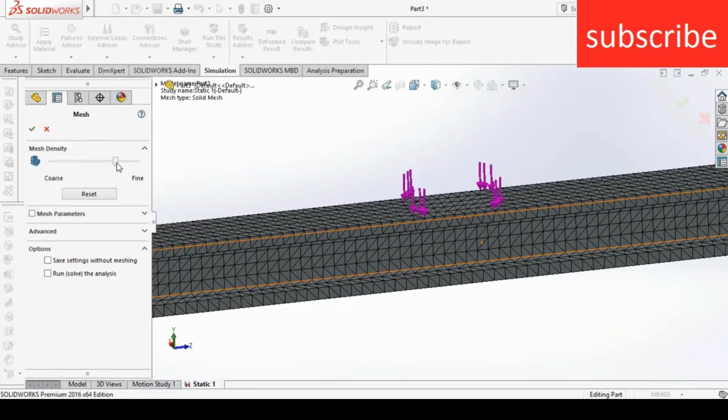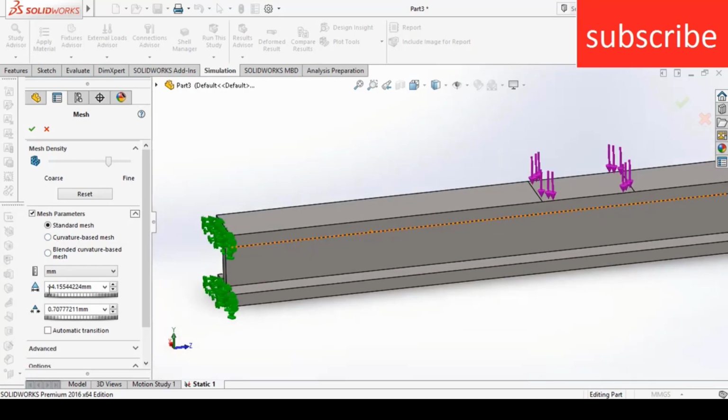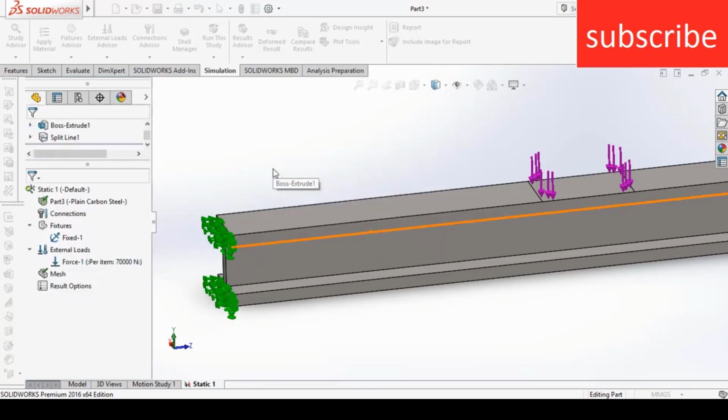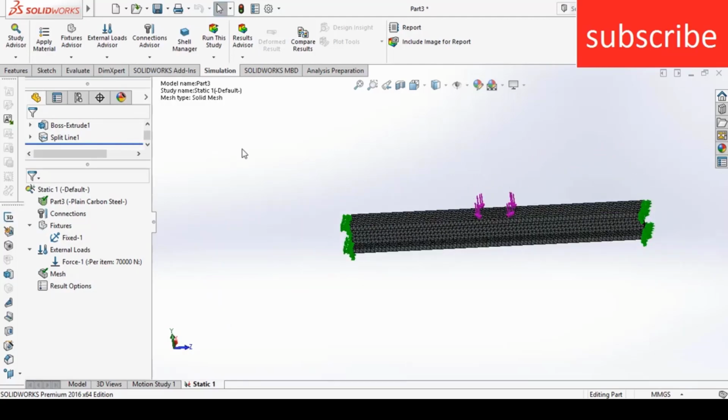The finer the mesh, the better the quality of the result. You can adjust the parameters like what should be the width, height, depth of your mesh parameters or nodes as per your requirement. In my case I just prefer this, normally this will do for me. Remember my main aim here is just to tell you how to do a simulation. So you can adjust and create whatever you want.